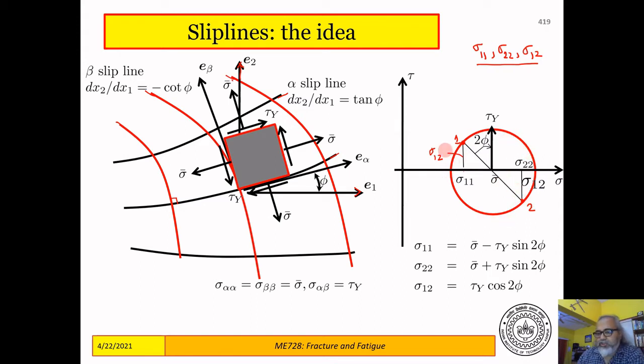And if I draw this Mohr circle, then I can identify two quantities. One is the maximum principal shear stress, which I obtain by turning the point representing plane 1 by an angle of 2 phi, which represents a physical turning of the axis by an angle phi.